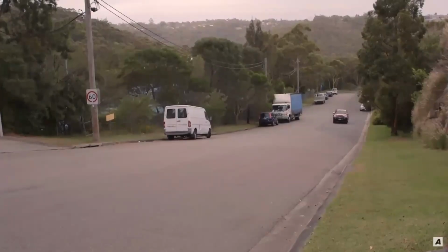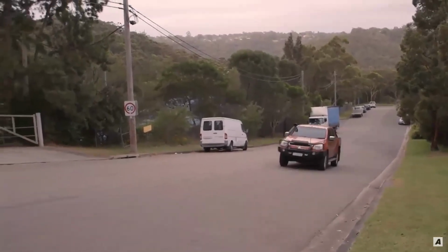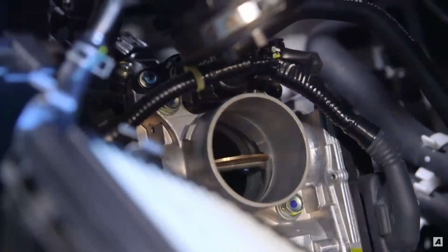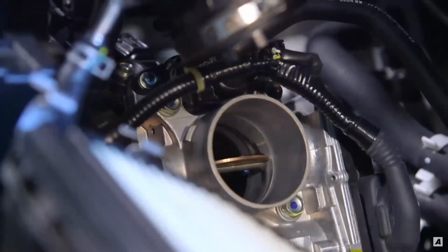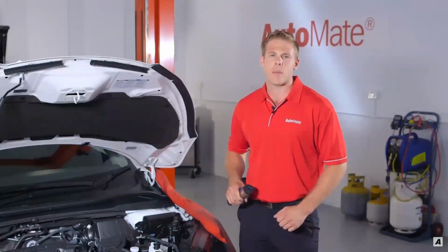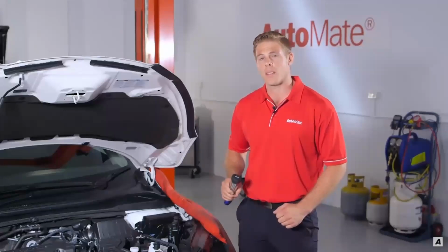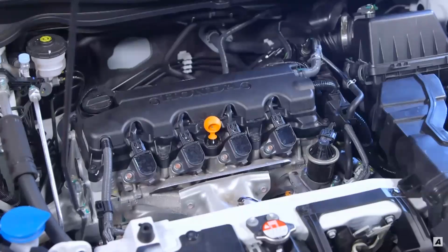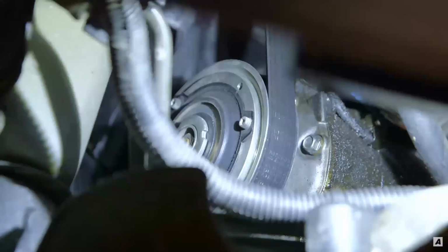The driver's torque request is communicated to the ECM via an accelerator pedal voltage signal. With this information processed, the ECM can command the throttle valve motor open or close, achieving the desired torque. The ECM can make adjustments to the throttle valve without the input from the accelerator pedal. Fast idle can be seen during cold start conditions or when the air conditioner has been turned on. The ECM may command the valve closed during a traction or active braking control moment, regardless of the driver's torque request. A TAC system on a common rail diesel has no control over the throttle valve assembly. The valve is normally in a wide open position.